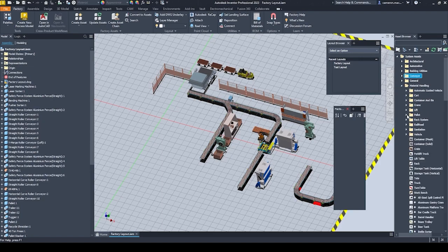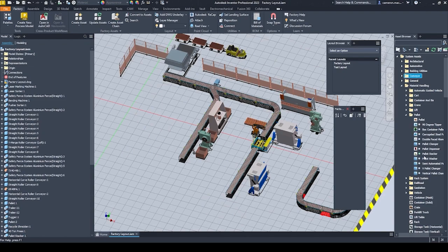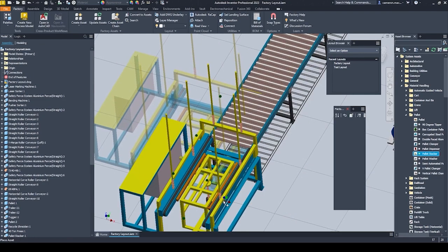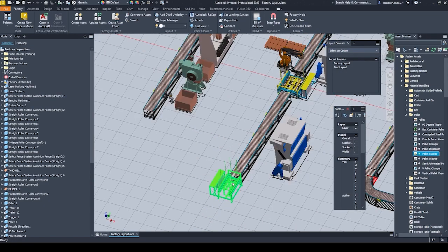assets and perhaps another palette or so. We've got the palette stacker, which is that one that's available there. If I again show you the same process using the same palette stacker, dragging it into the Inventor workspace, you can see how it's giving me those snap points once more. So I could then just place it in using that. It takes a little longer to place those in, but now it's automatically giving us the scaling compared to the conveyor belt itself as well.